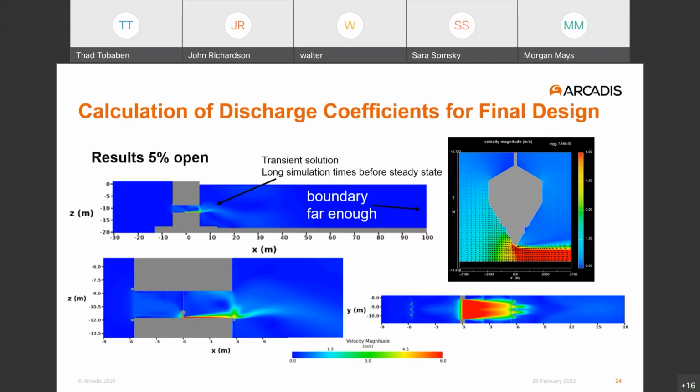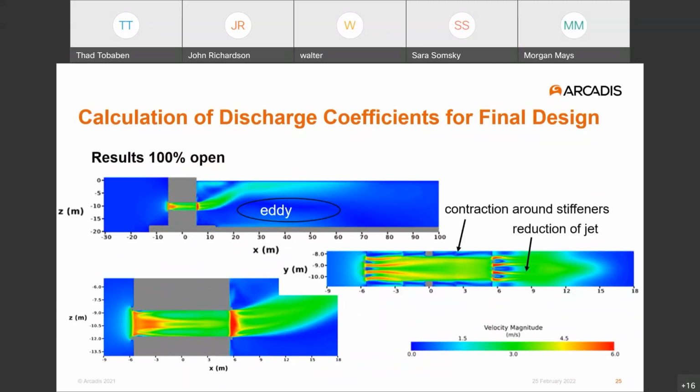The flow patterns in general are about the same with the design changes made. For the 100% open case, there are a couple things to point out. One thing that wasn't expected was that the jet flow showed in these simulations on the downstream side of the gate openings, the jet flow showed actually attaching to the water surface, or not going down and attaching to the bottom. That's something that was studied with the physical model and is also relevant to mooring design as well.